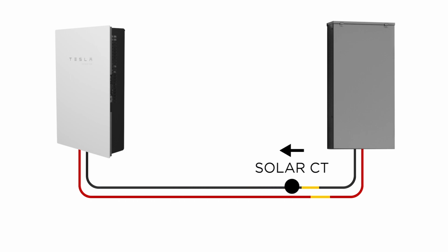It is preferred to monitor a solar inverter with only one CT, and then configured with the X2 modifier during commissioning. Because solar production from split-phase inverters is balanced, total solar output can be calculated with a single CT. This reduces the cost and labor needed for installation.